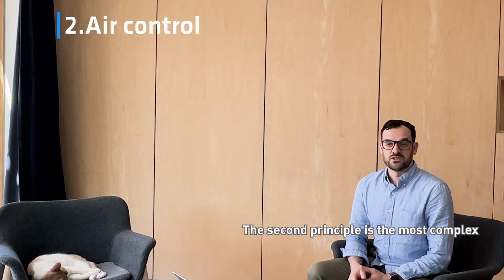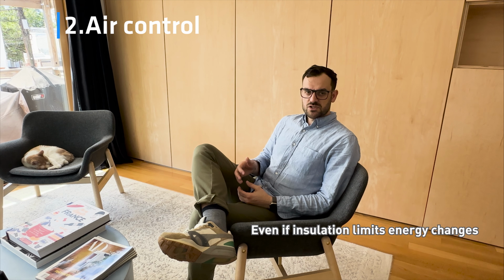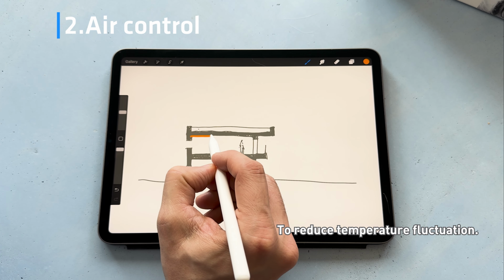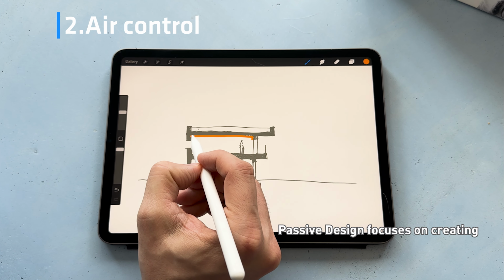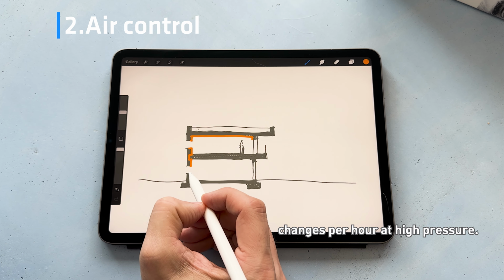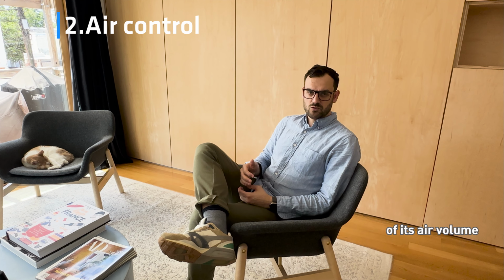The second principle is the most complex to achieve during construction: air exchange control. Even if insulation limits energy exchanges through materials, energy leaks can still happen via air circulation in and out of a building. To reduce temperature fluctuations, passive house design focuses on creating an airtight envelope so that there are no more than 0.6 air changes per hour at high pressure. In plain English, this means that without any exhaust fan, the house should have no more than 0.6 of its air volume going in or out of the house every hour.